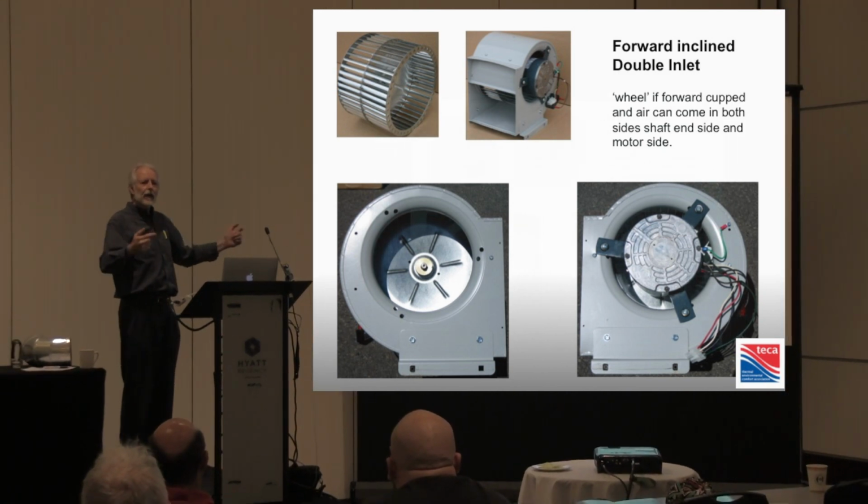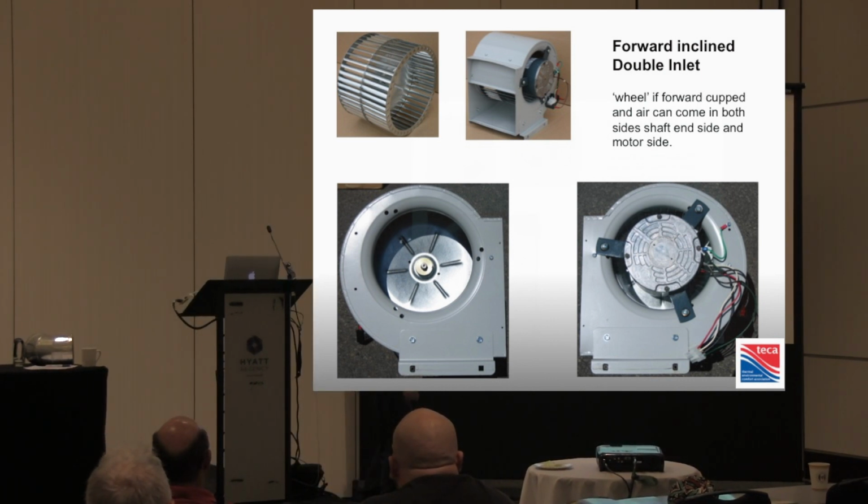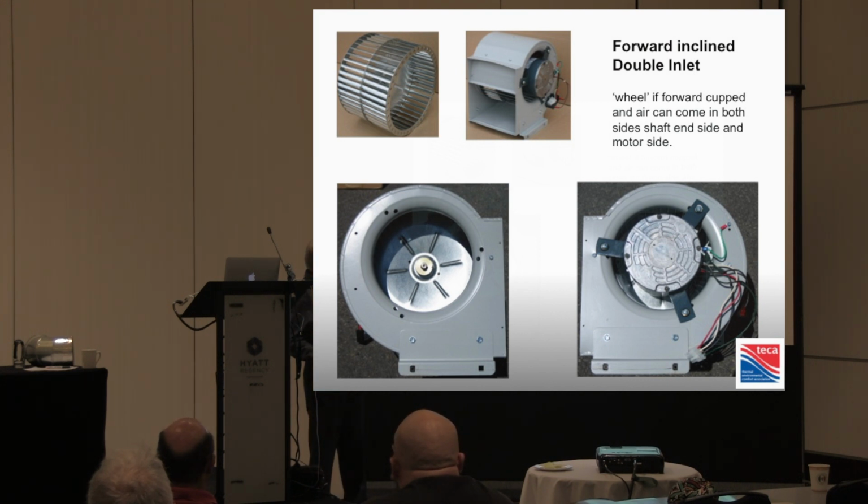That is the direction that all these fans work for every product that's heating and cooling in North America. It's called double inlet because air can come from both sides, and it's got a very heavy gauge steel divider between the two because that gives you a very, very rigid wheel, which you can put right onto the motor shaft. It saves you a bunch of belts and pulleys and jack shafts, and you end up with a package that's extremely compact. The manufacturers love this package because it's really, really small to get into the appliance that you've demanded become small.